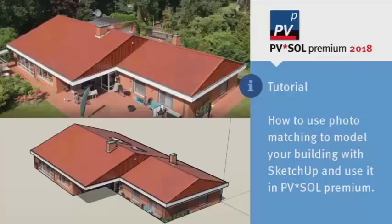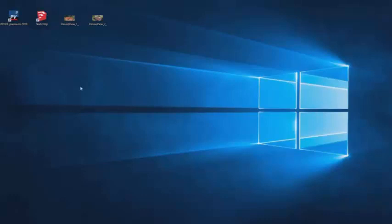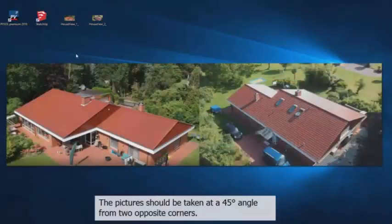In this tutorial you will learn how to use photo matching to model your building with SketchUp and use it in PVSOL Premium. You will need 2 pictures of the building you like to model, SketchUp Make or Pro, PVSOL Premium 2018. The pictures should be taken at a 45 degrees angle from 2 opposite corners.